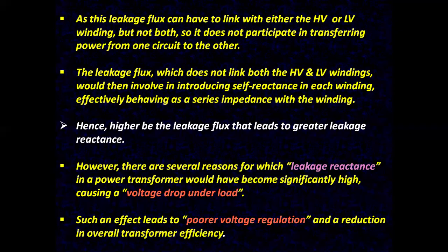The leakage flux, which does not link both the HV and LV windings, would then introduce self reactance in each winding, effectively behaving as a series impedance with the winding. Hence, the higher the leakage flux, the greater the leakage reactance.